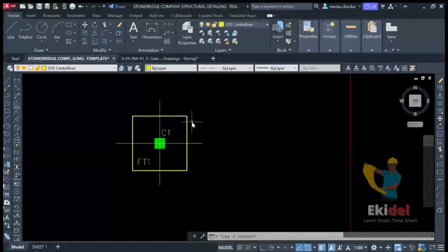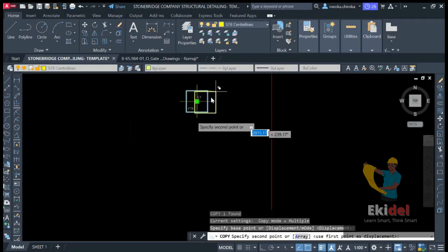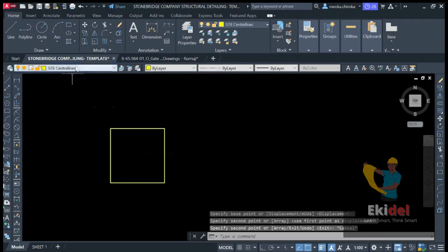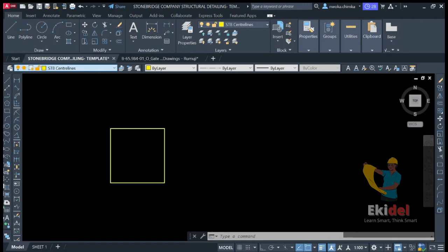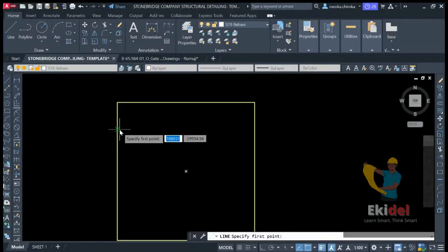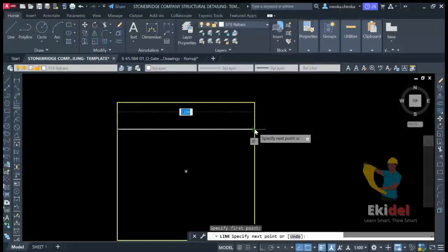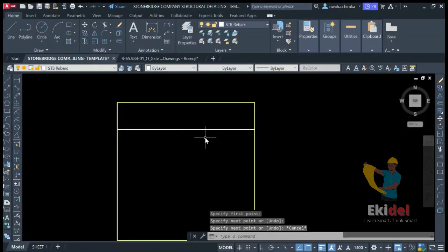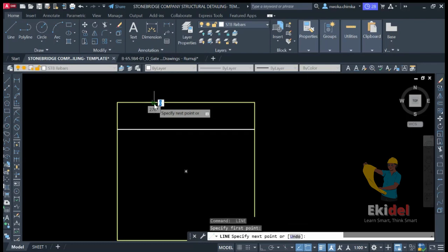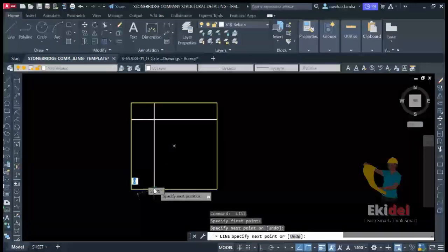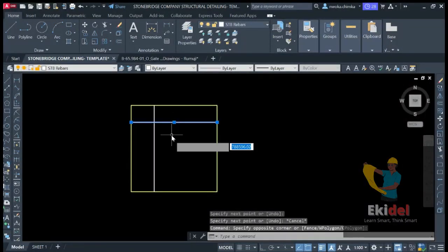this foundation footing. So right now, we'll just copy this first of all, paste this here first of all, and then go to this place to draw the reinforcement. So go here right now and activate STB rebars. You can see here STB rebars, and then we'll click on this place right now. Click at this point first, and click at this point to establish our first horizontal reinforcement on the X direction, and then here again to establish for the Y direction. Now we just take this again downward again,